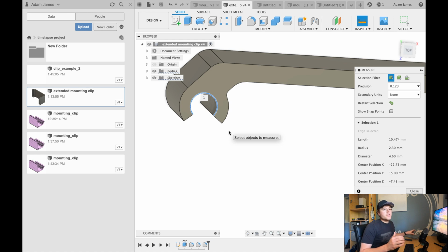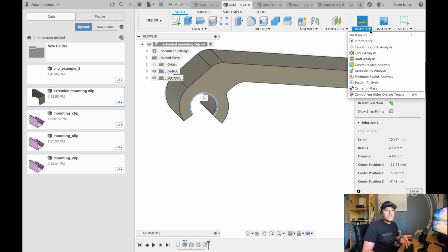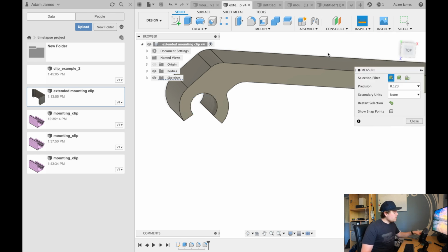Now, the purpose of this is not necessarily to eliminate using a caliper, right? If I already have the part in hand, it's much more accurate to take, say, a caliper, measure these dimensions, and then whip up a CAD remix. But what this route does is it saves a step, right? So what you can do, without needing a 3D printer, is take those STL files from Thingiverse, insert them as a mesh in Fusion 360, and then take reference dimensions using the measure tool within Fusion 360.